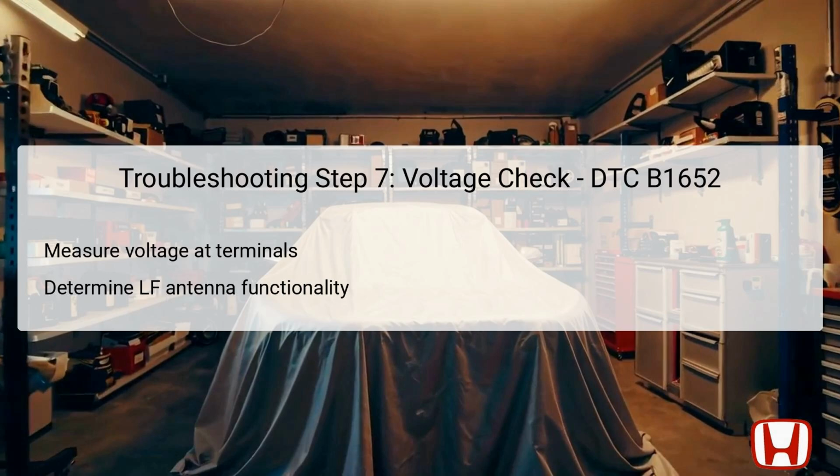If voltage is present during this check, it indicates that the power supply to the LF antenna is functional, suggesting the need to replace the right sliding door outer handle. On the other hand, if no voltage is detected, it signals the need to investigate further into the wiring and connections downstream of the control unit. Thus, measuring voltage serves as an essential diagnostic step in verifying antenna functionality.